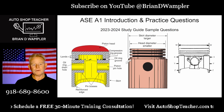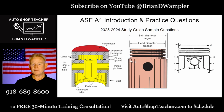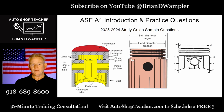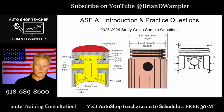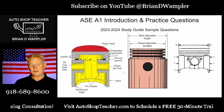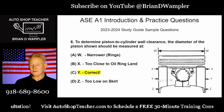And then here right below the oil groove, as illustrated by X on our right image, that's right below a ringland, okay? And you could measure this piston anywhere you wanted to, okay? But if you wanted to jump straight in for where most likely the widest spot is going to be, it's going to be here at Y.